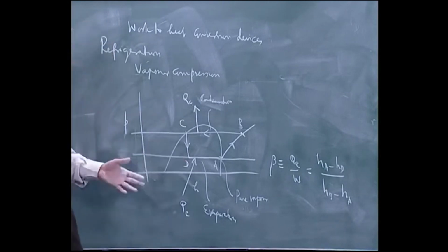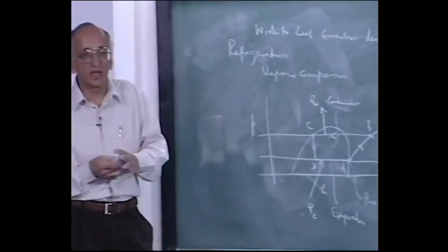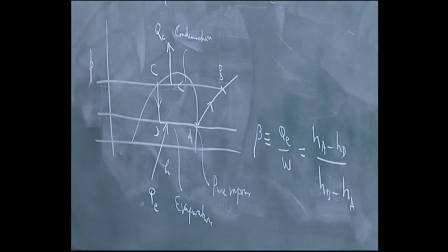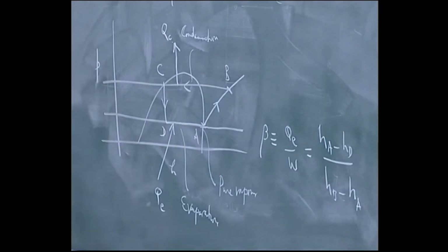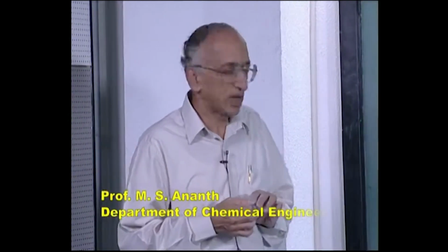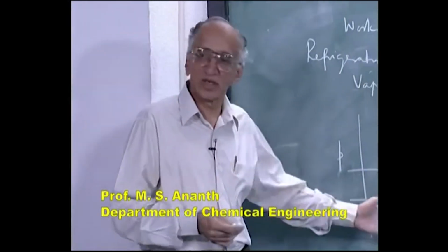This is vapor compression. What we will look at is mixtures where you do absorption refrigeration. You will find that for large scale, absorption refrigeration is much better. Here you have a compressor with moving parts, there you do not have the same; what you do is absorb the gas in a liquid and you take away the gas in a liquid at a different temperature. You can use this difference in solubilities and the enthalpy of dissolution to extract some refrigeration out of it.